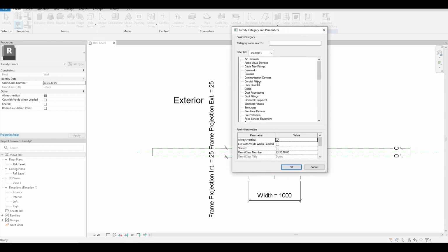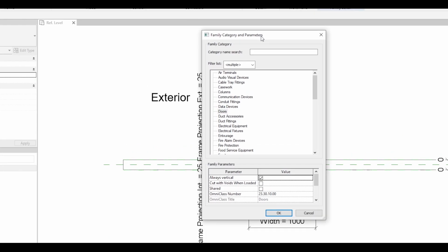By default, it's within a door category. Now this might seem obvious, but it's quite important to have the correct category for your Revit family. Often within a project, you have schedules, visual settings, and templates that rely on reading this category-based information.